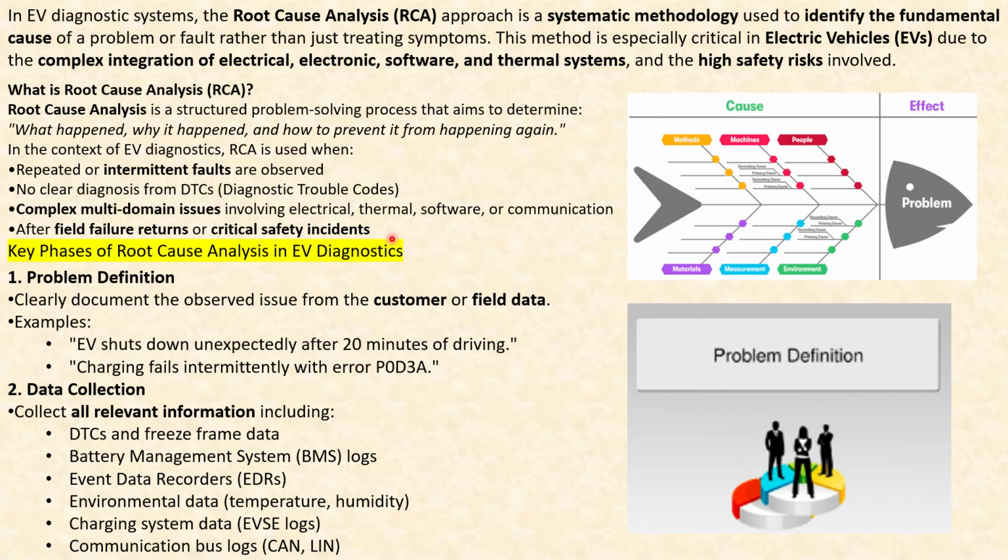All right. So this is the exact moment where root cause analysis is used for electric vehicles. And when it comes to the key phases of root cause analysis in EV diagnostics, first you define the problem. Clearly document the observed issue from customer or field data. Examples: EV shuts down unexpectedly after 20 minutes of driving, or charging fails intermittently with the error P0D3.